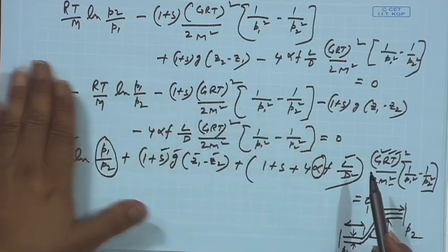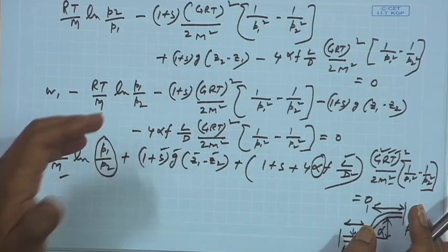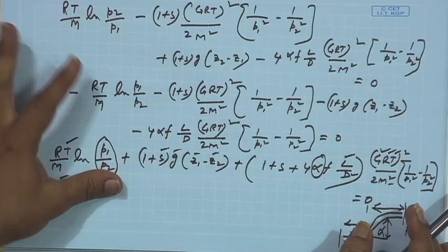Once alpha of that system is known, then subsequently for a different unknown pressure combination, you can find out either P1 or P2. Given P1 or P2, alpha you have already determined for that system, and by knowing all other parameters like length, height, distance, diameter of the material, you can also determine the pressure. Because as I said, in this kind of process where you are pneumatically conveying from one place to another, how much energy is required is your fundamental question.